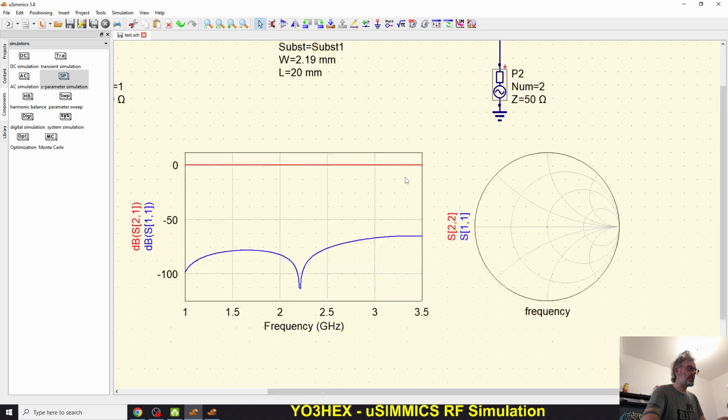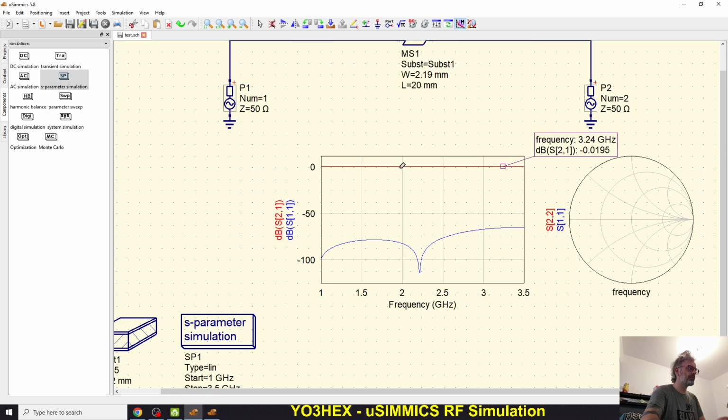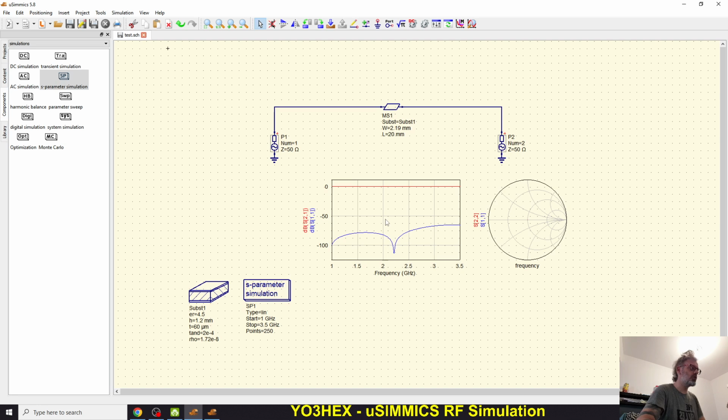The losses are almost negligible. We are having less than, I don't know, something dB, and it's kind of the same all over the place. Okay. The impedance match on the return loss, of course, it's theoretical. You will not have something like this in reality, but it's good to see. We're having minus 114 dB for the return loss. If you are going to have something around minus 24 to minus 40, be happy with it. It's all good. But again, it's just a simulation.